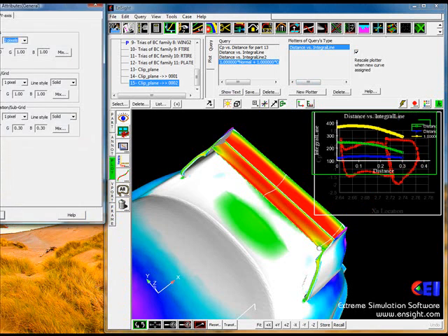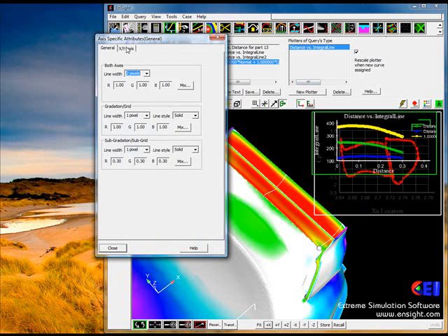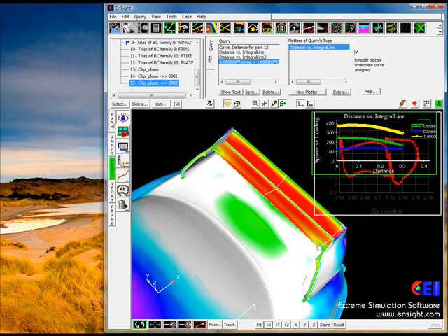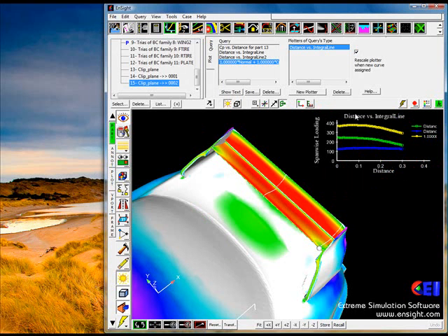and look at the min and max values on the y-axis, and say I'd actually like my minimum to be 0. My maximum is okay. And we'll look at this as spanwise loading. Now we've got ourselves a spanwise loading of both the flap, the main plane, and the total as we go across.